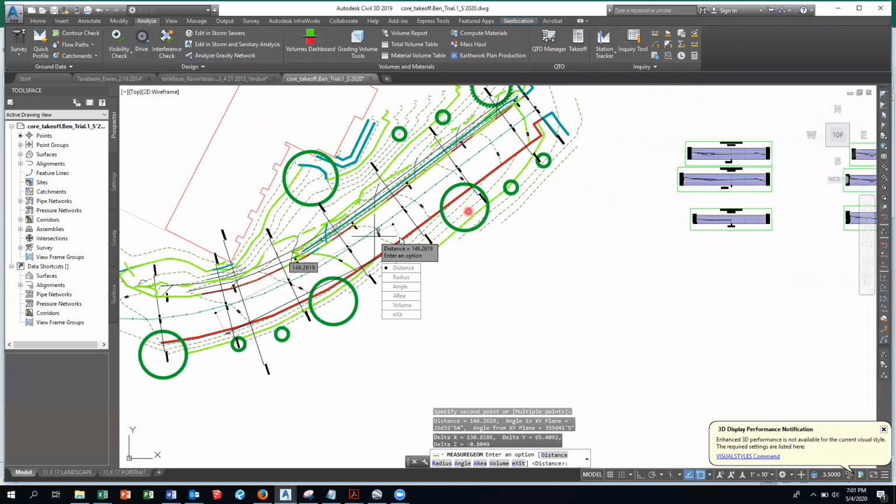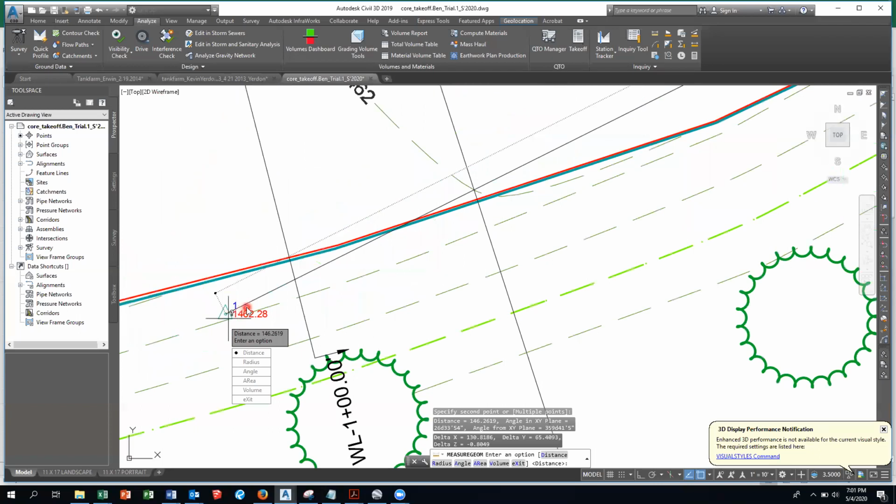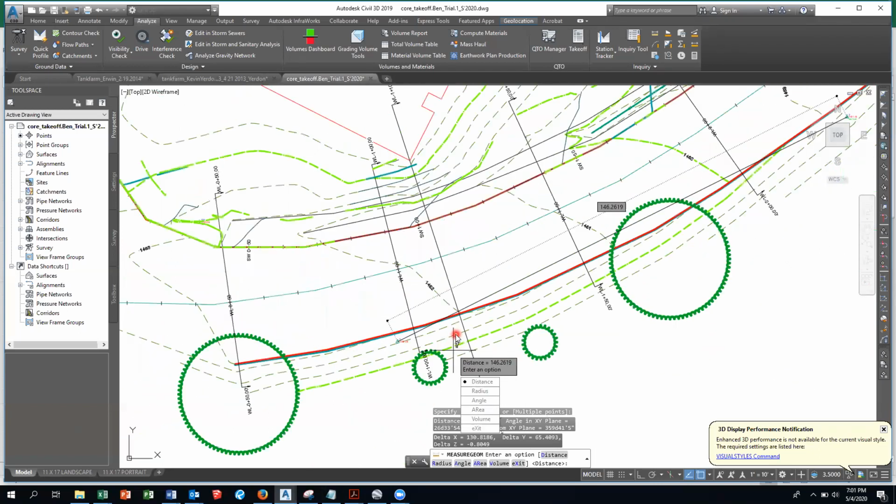Right? Here's the road. Here's the roadside ditch. So if the sidewalk is going through here, maybe we want the sidewalk over here. All right? Either way, as you design it, you can get coordinates for it, northing and easting, and then you can do a radial layout set up on delta 1 and shoot every part of that sidewalk project that is within view of delta 1. So again, a very, very powerful tool.